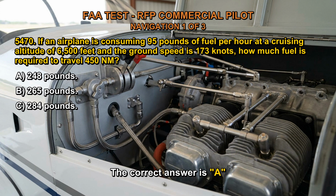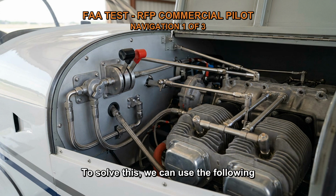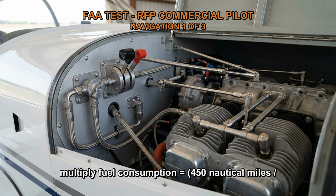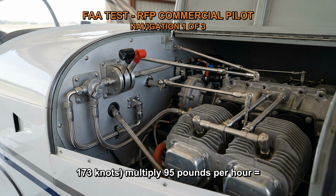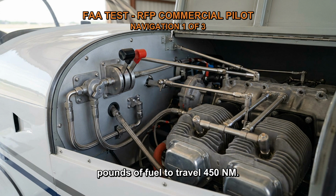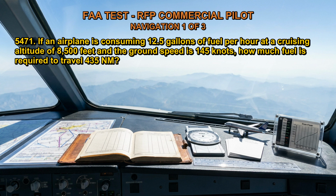The correct answer is A. To solve this, we can use the following formula. Time equals distance divided by ground speed. 450 nautical miles divided by 173 knots, multiplied by fuel consumption of 95 pounds per hour, equals 248 pounds. Therefore, the airplane will need 248 pounds of fuel to travel 450 nm.